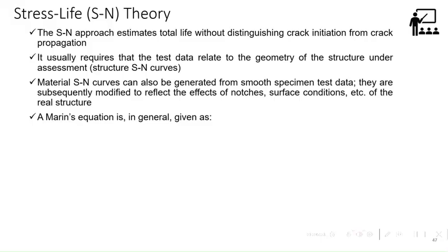So there you will find, of course, it covers many domains, not only fatigue, and an endurance curve is available for the half wing also. This endurance curve is available at the specific component level, but the majority available is the material SN curve. So the emphasis, the driving point, is that it is preferred to have the SN curve available for that particular component, and then there is nothing to worry about. Your prediction will be as accurate as possible, and there is no conservatism in that.